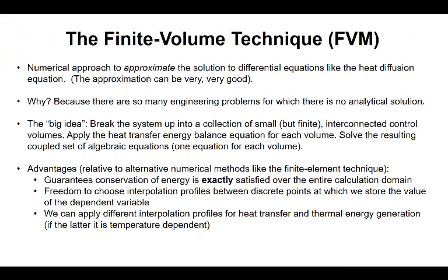In this heat transfer class, I will teach you a technique known as the finite volume technique. I denote the finite volume technique with FVM, finite volume method. The finite volume method is a numerical approach to approximate the solution to differential equations like the heat diffusion equation that defines the heat transfer for multidimensional conduction heat transfer problems.